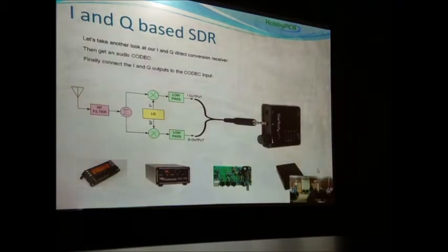But like I say, we have an LO output, and I know that people have built converters to convert everything up to 2 megahertz, kind of 5 megahertz higher, so it comes out in the 40 meter band, and you can program it so that it does at least receive on 160 and the other two new low band ham bands. And we may eventually put together a 2 and 6 meter converter for it, because again, like the local oscillators there, all we need is a mixer.